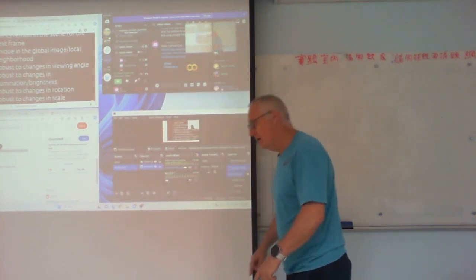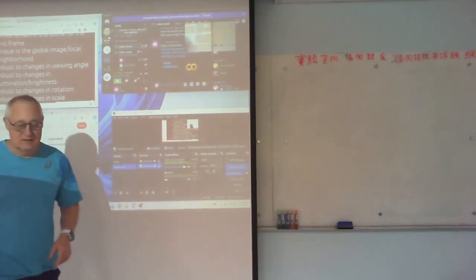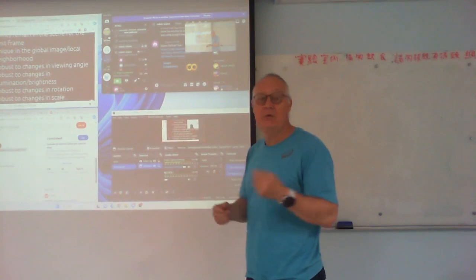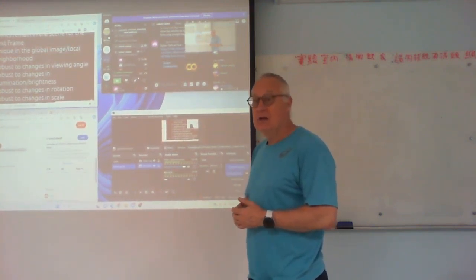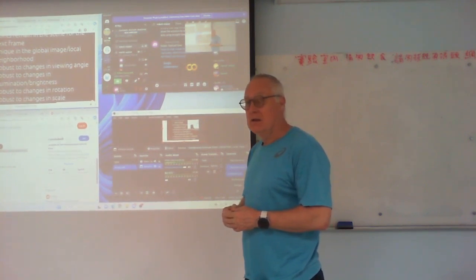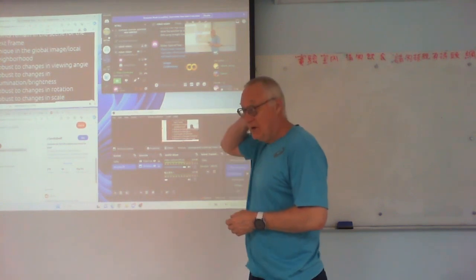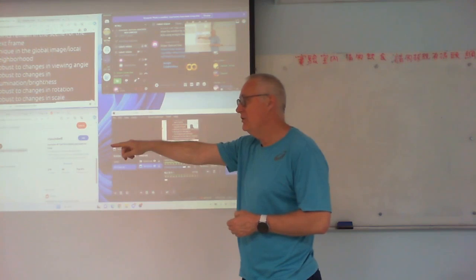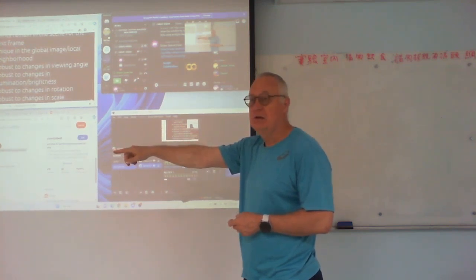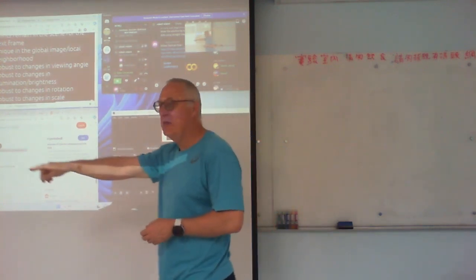But of course, if I run much faster, then that association between the previous feature point and the next feature point may get lost. So we want also to memorize the number of intersections that we have passed. Or is this just an example? This is just an example. If I look at my ORB feature detector and I use features on the blue chair, then those would be better points, right? Because there's no other blue chair here.